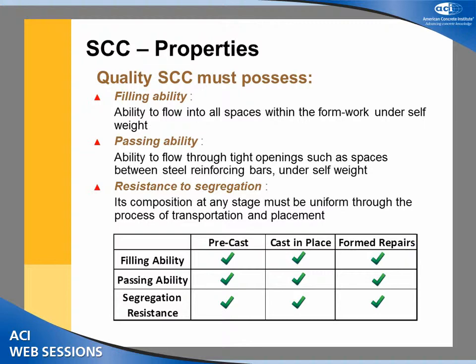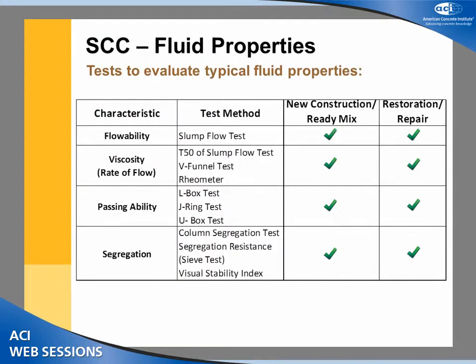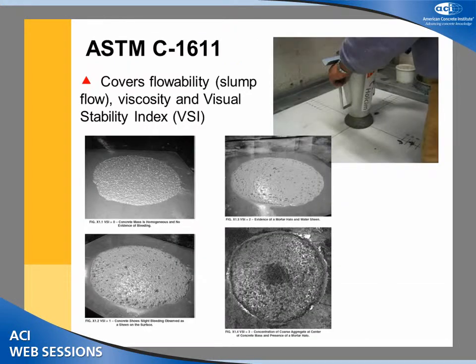These properties are similar when it comes to SCC, whether it's coming out of a bag or out of a precast facility. Again, the fluid properties of the SCC are exactly the same, whether you're talking about new construction, ready mix, or SCC coming out of a prepackaged bag. When it comes to flowability, passing ability, and segregation, these are the test methods used for conventional SCCs, and the same test methods are also used for SCC sold in the marketplace for repair applications. We're all familiar with these tests.